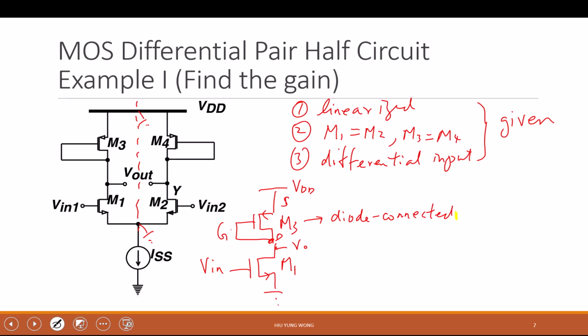The bottom one is NMOS. So this is source, this is drain, right? Because the source is connected to the lower potential. And this is gate. So the input is to the gate, the output is from the drain, and the source is grounded and is loaded by something called a diode connected load. And as a result, what is the gain?